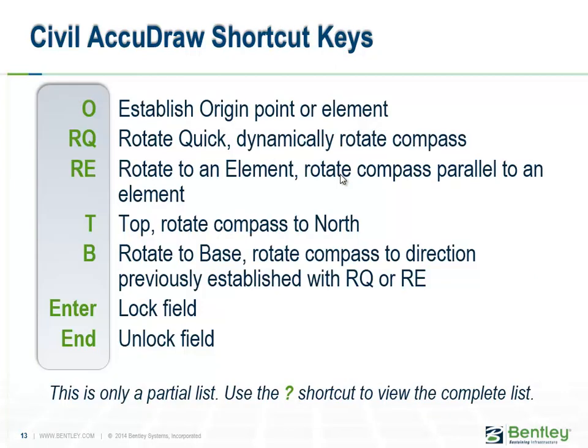Shortcut keys direct Civil AccuDraw to perform an action such as establish an origin, rotate the compass, or lock a value into an input field. Here are several shortcut keys you will find very useful when working with Civil AccuDraw. As your Civil AccuDraw skills increase, you may want to explore additional shortcuts to unlock even more power in this tool.